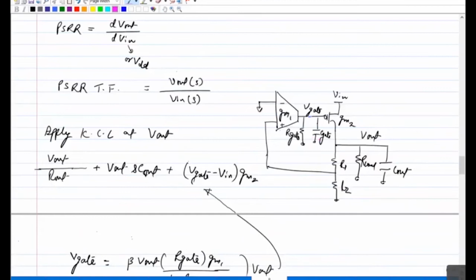So you take the Vin only, when I say Vin, only the AC component, and add it at the V gate. You take the DC component through feedback, which is the required DC voltage to regulate the output, and take the AC component of Vin with the same value and couple them together.